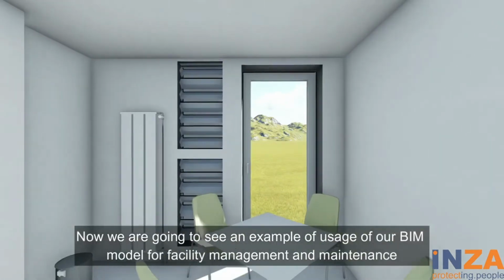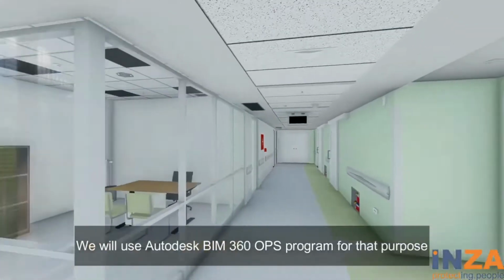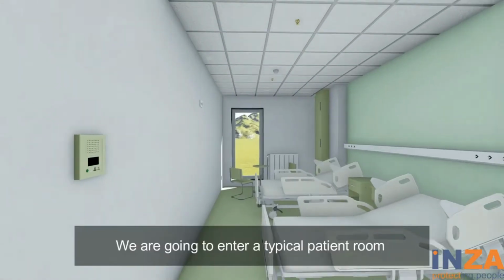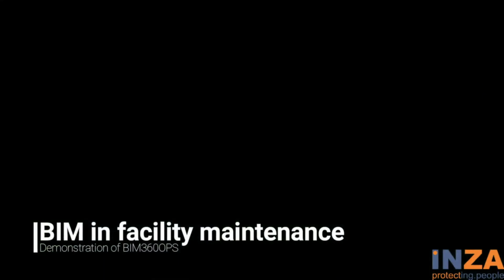Now we will see an example of usage of our BIM model for facility management and maintenance. We will use the Autodesk BIM 360 program for that purpose. We are going to enter a typical patient room where, as an example, we have an above-bed medical unit that was imported from our BIM model to the application.